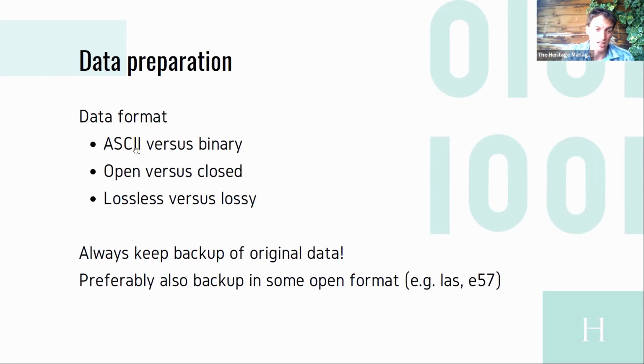So in most cases, it's advised to work with a binary format, and preferably a binary format that is open access. So for example, here I mentioned the LAS format if you're working with airborne data, or the E57 data format that we are also using in the demonstrations. These are open formats with an open specification published on the internet, so you can use them, you can modify them. You are not stuck with one single scan vendor or software developer.